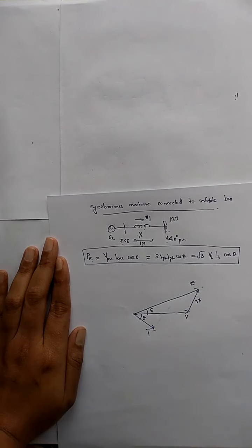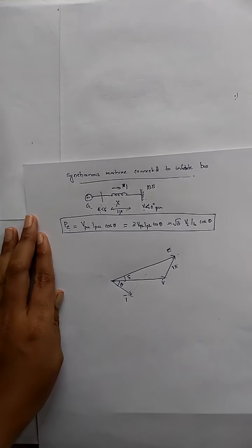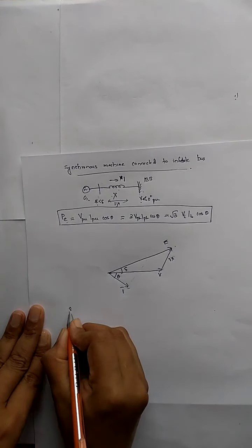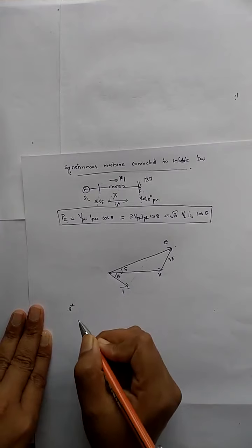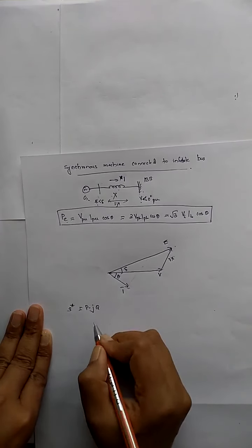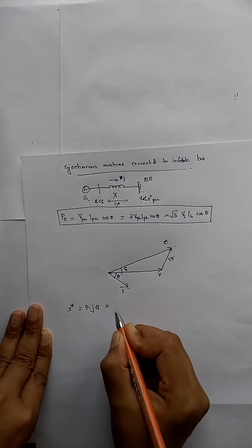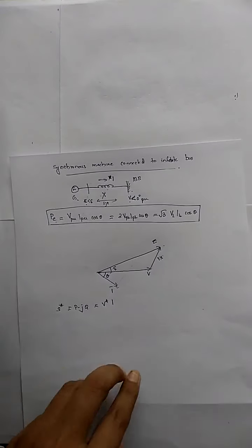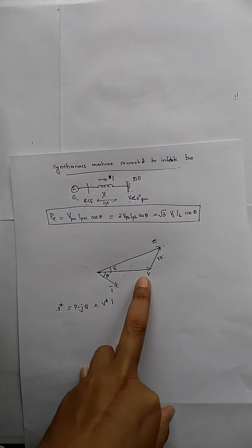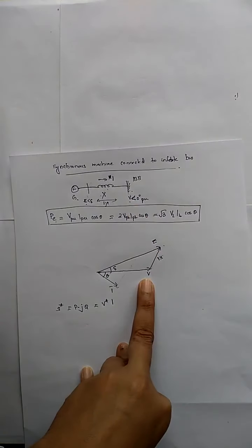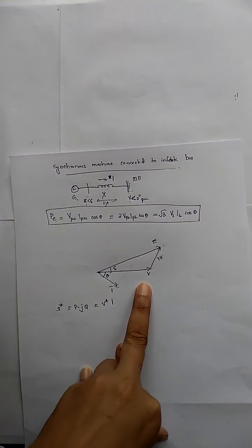Now what we have to find out is the power transfer. I am starting from the apparent power. The apparent power will be equal to P minus jQ, as we started in our load flow analysis, or I can write it as V conjugate into I. But the V has reference angle 0, so V conjugate will have magnitude V alone.